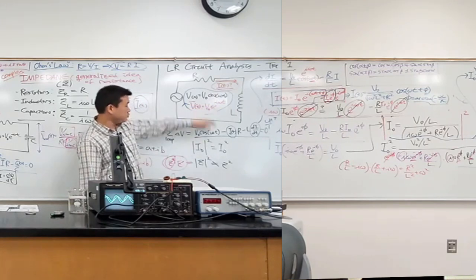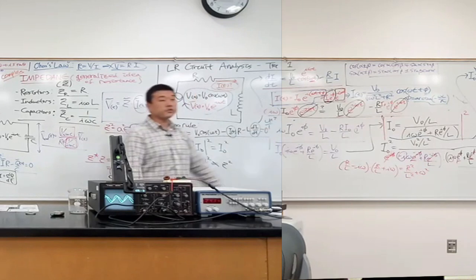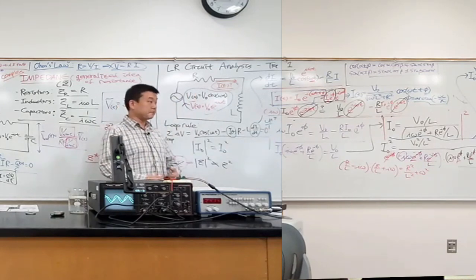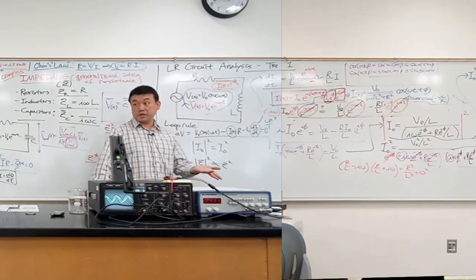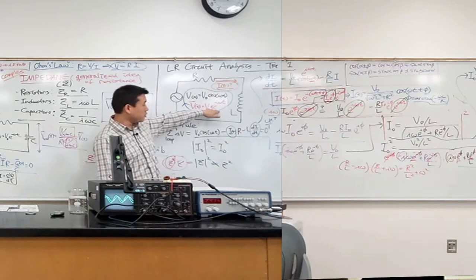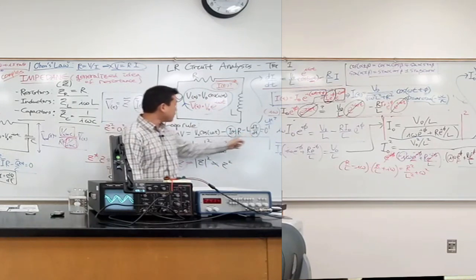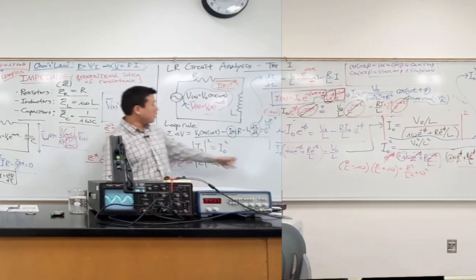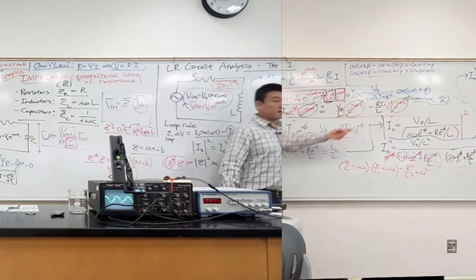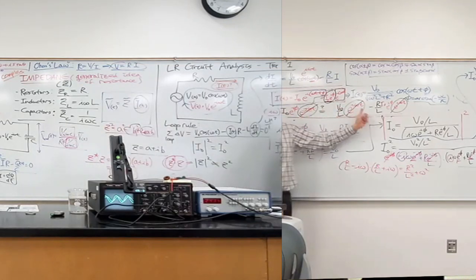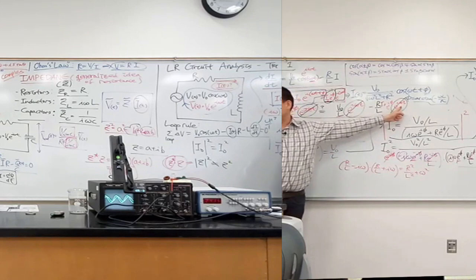So using this, you can actually work through all these circuits like you did a DC circuit. Because with the complex exponential, one of the things it does is it makes these calculus problems into an algebra problem, because this e to the I omega t term will almost always cancel out.